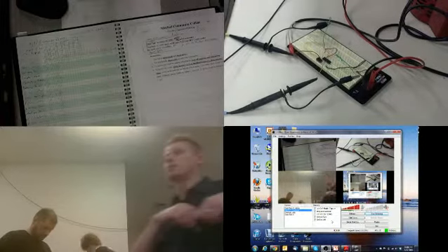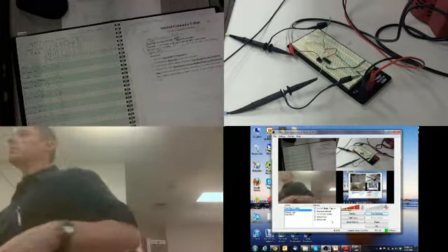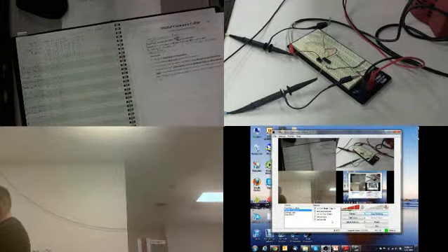Two questions. One, okay, we have the signal that you have. It's working. That's good. But I wondered why this happens. What is that? This is just an LED. But when I hook up the LED from signal 3, look how much it drops in voltage. Because you don't have a current limiting resistor. You have to have a current limiting resistor.